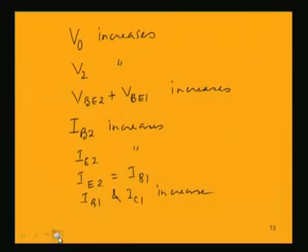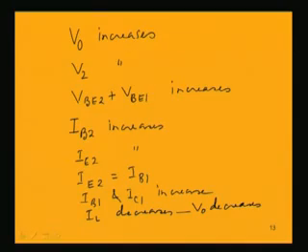So the ultimate effect is that IL, not IL1, IL the load current, decreases, so V0 decreases. Initially V0 increased, but finally V0 decreases, which means it is kept at a constant value. So this is one type of shunt voltage regulator.